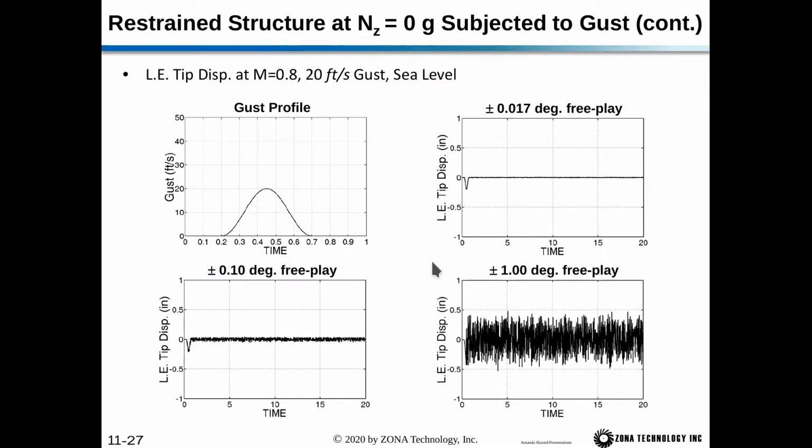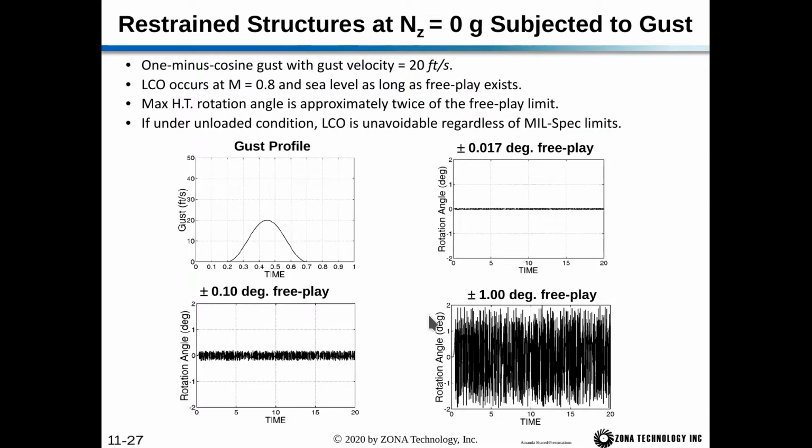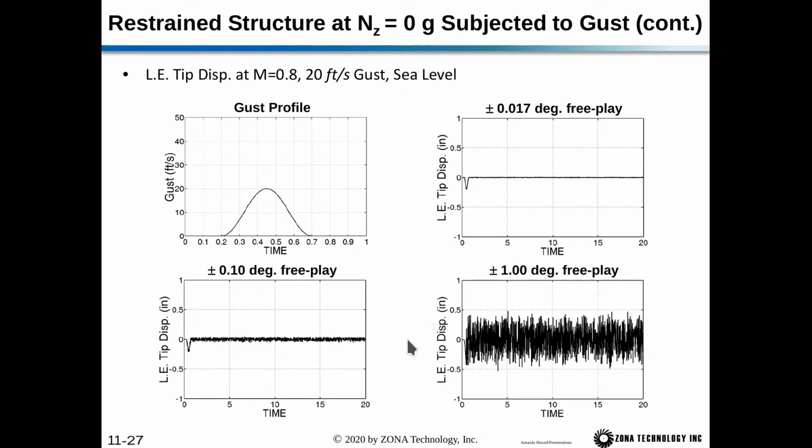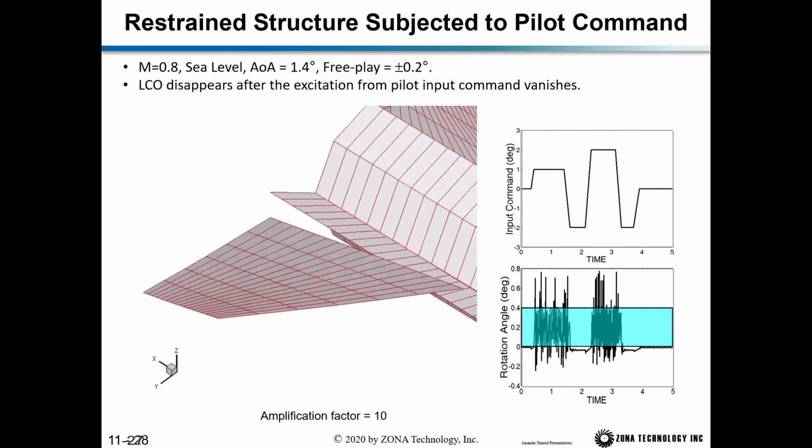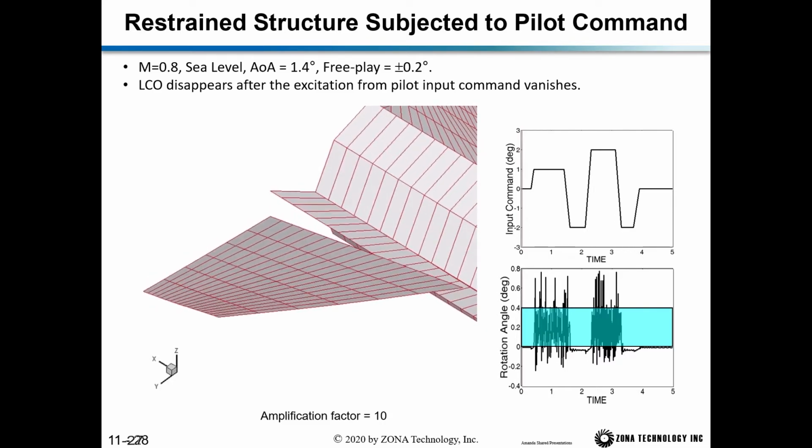This is the leading edge tip displacement, whereas the last figure was the rotation angle. So our leading edge tip displacement, you can see with 1 degree free play, we get a large response. When we cut that down by an order of magnitude, we cut our response down by an order of magnitude. So next we have a video here of what the response looks like when